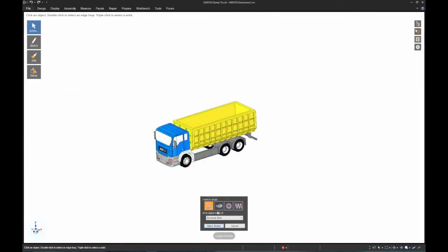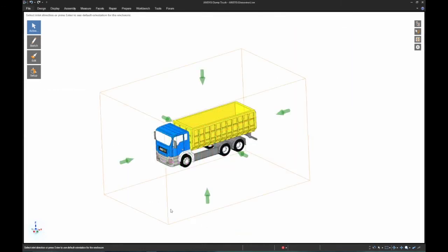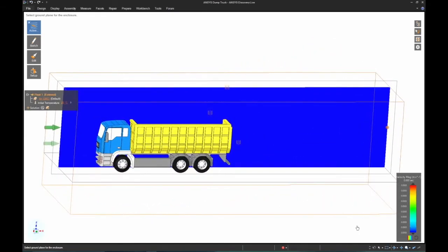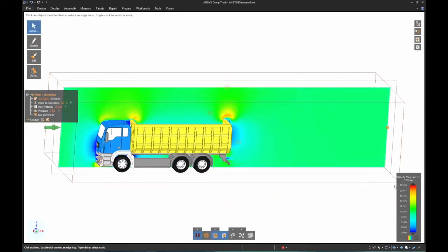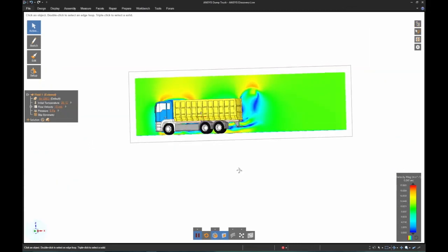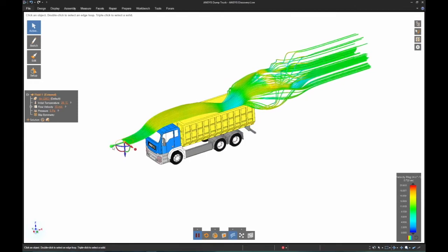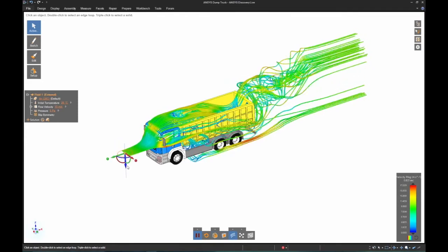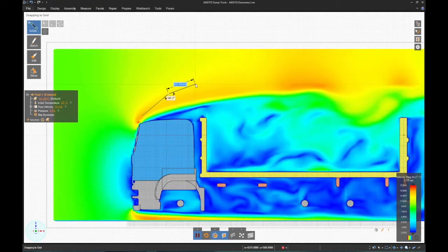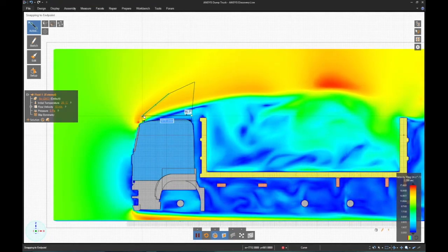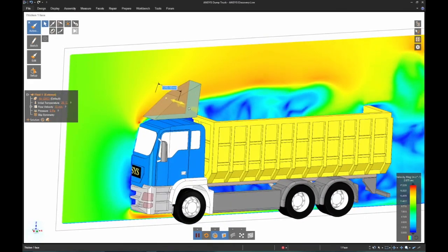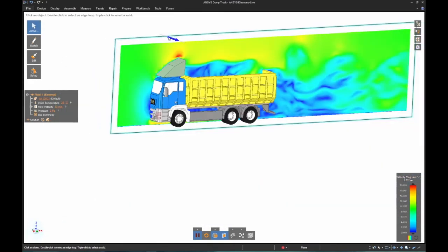In a final example, we'll jump into an external airflow study to not look for highly accurate lift and drag values, but to observe trends in the airflow around the vehicle. And as before, setting up a simulation requires minimal inputs to get instant simulation results. What I'm curious about is the effect that a top deflector will have. With a handy sketch tool, I can mock up my concept and transform it from 2D to 3D. The solution updates, and I have instant feedback.